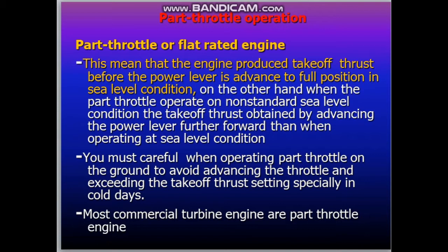So when the aircraft is flying in non-standard sea level, the power lever, or the throttle, will be further forward than when the aircraft is at sea level. You must be careful when operating part throttle on the ground to avoid advancing the throttle and exceeding the takeoff thrust setting, especially on cold days.